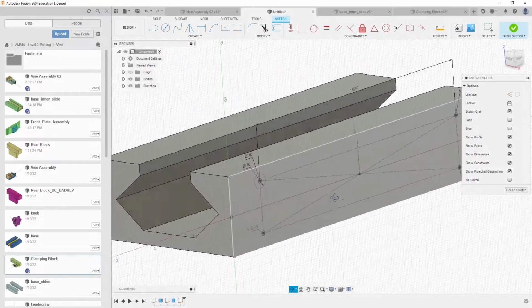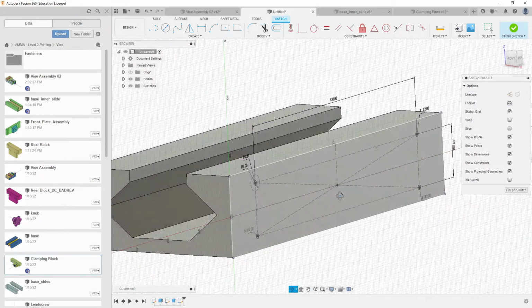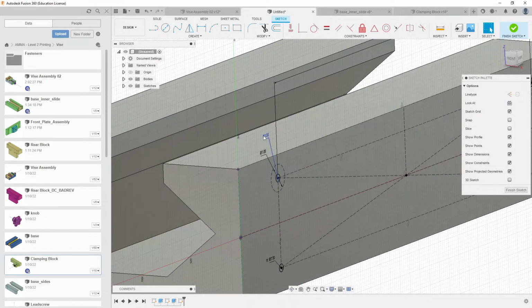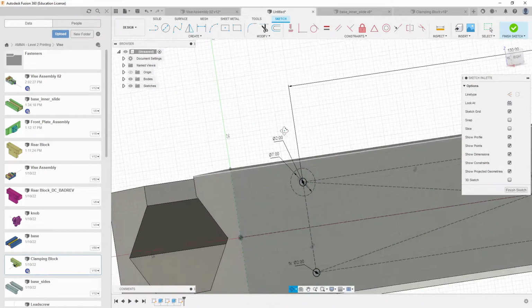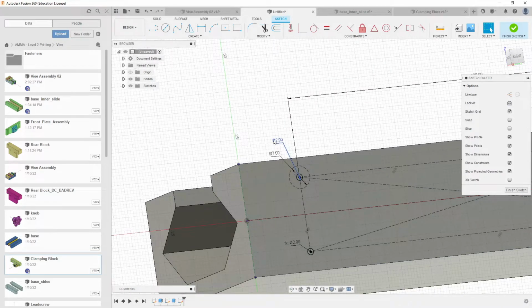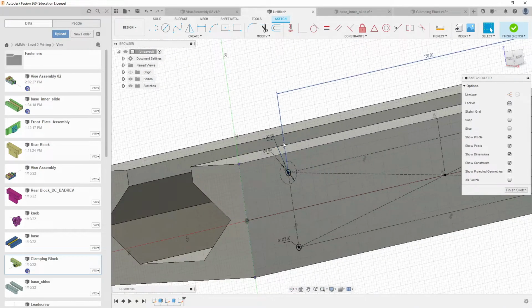Now, we could do a heat set insert on this, which might be the future of this. Then what we end up doing is we enlarge and embiggen. We'll open this hole up to something like 6mm, 5mm, whatever the width of the heat set insert is, less a tiny little bit, and shove that in there. That would be great if you get it perfect.